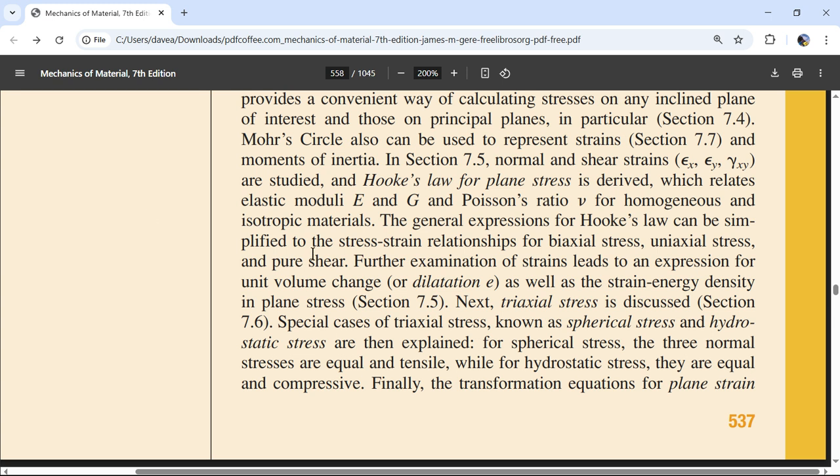I divide by 0.002, and you basically get 58 divided by 2 is 29, but dividing by 0.001 is moving the decimal place 3 places, so I get 3 extra zeros, so I get 29 million. A lot of different ways to do that, but it is useful not just to memorize that the modulus of elasticity for steel is 29 million psi, but to know that if you multiply 29 million by 0.002, you get 58,000. That's just the linear relationship, the equation of a line, and the same thing is true for the shear modulus.